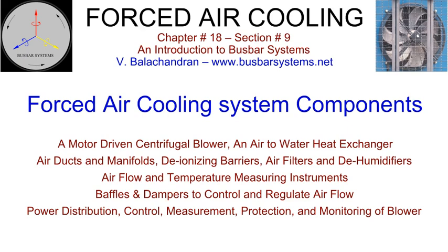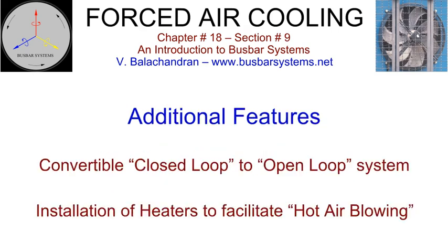Control panel for distribution of power, control, measurement, protection, and monitoring of blower system. Redundancies may be built as required. Many project specifications call for a convertible closed-loop system, incorporating a mechanism that enables a closed-loop system to be converted into an open-loop system in the event of a failure of the air-to-water heat exchanger. During the changeover, the temperature of the conductor and enclosure shall remain within the specified limits for such a contingency.